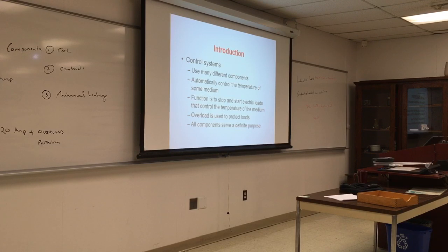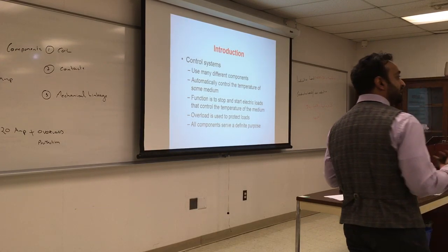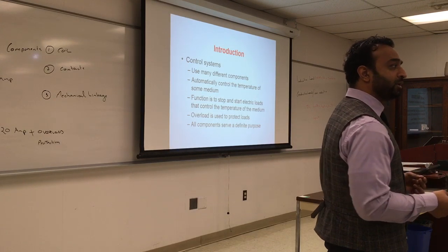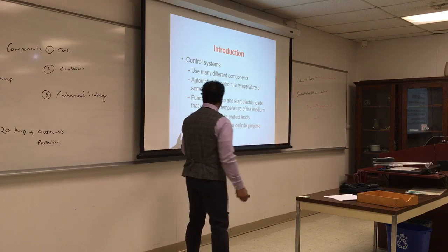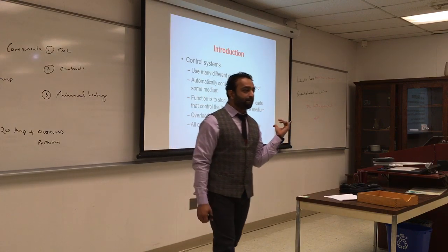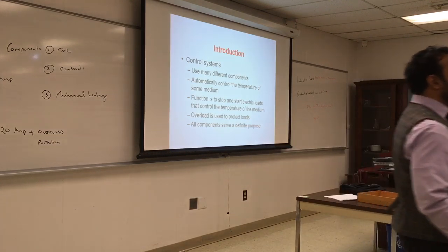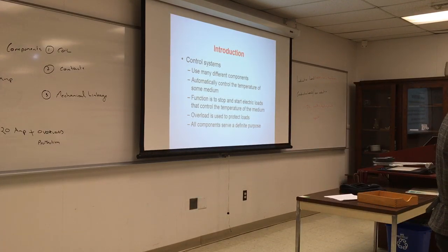We just do only one thing, which is what? Putting in a temperature, and everything runs by itself. And that's thankfully because we have some kind of control components, and we have timers, functions. And again, sometimes the system fails. So if the system fails, we don't have somebody physically there to watch all the input, so we need to have overload protection. We also have low water cutoff, high water cutoff. So for the concept of control, you always have to have input and output and limits.